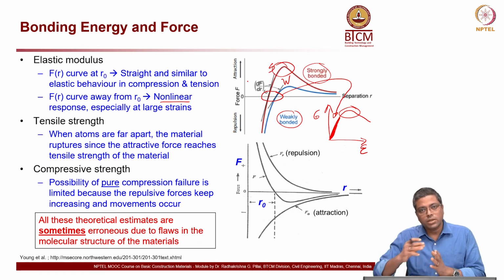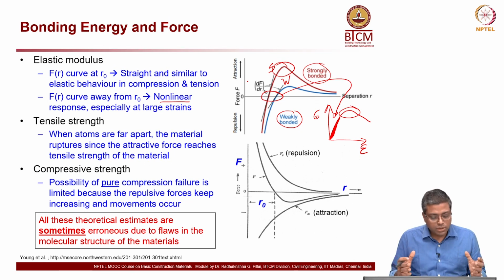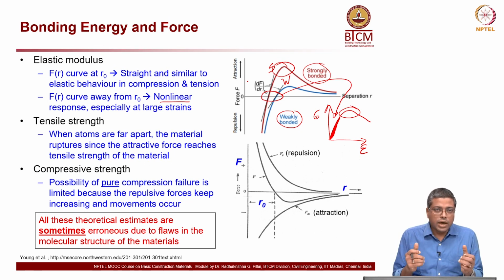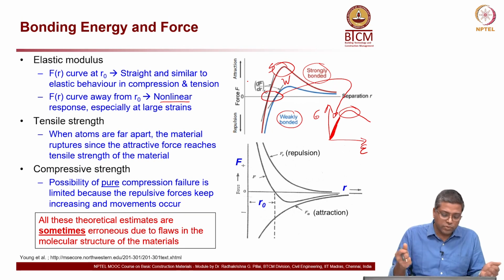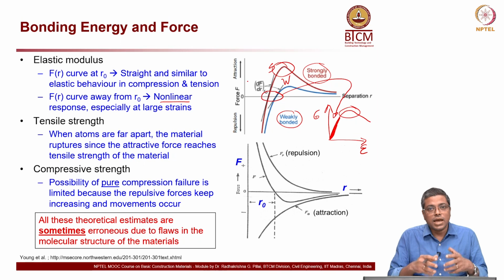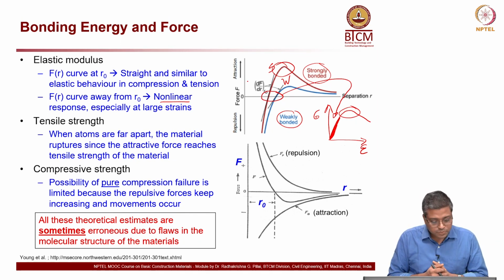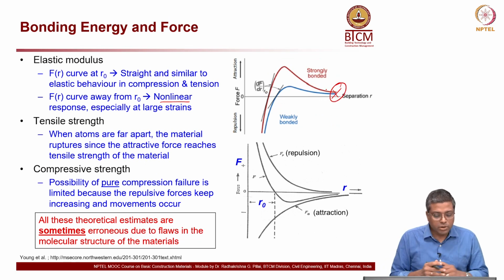But as you keep pulling, the curve becomes non-linear. Now, tensile strength: when atoms are far apart, the material ruptures, or at a point where the reaction provided by the material, the attractive force, is less than the pulling force, then the material starts rupturing and fails. And that is the point over here on the right end.